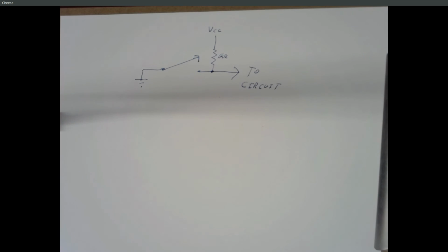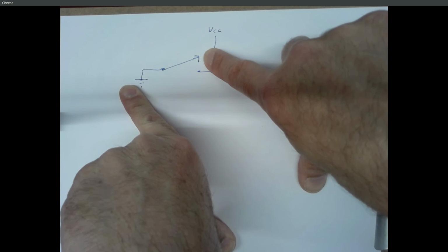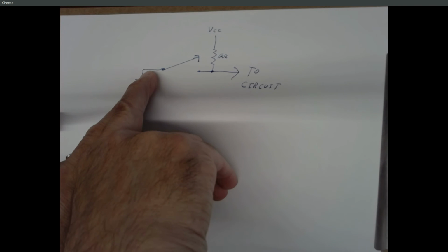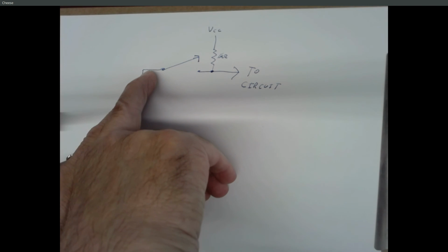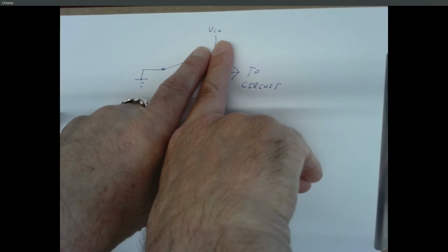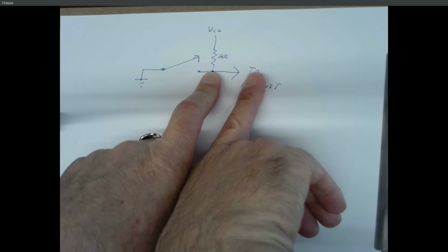Because it's trying to pull infinite current, right? And the circuitry inside is saying, no, you can't do that. So that won't work. If you put the resistor over here, that will kind of work, but it could damage your circuitry. Because you have 5 volts with no resistor going into your circuit, theoretically that's infinite current.